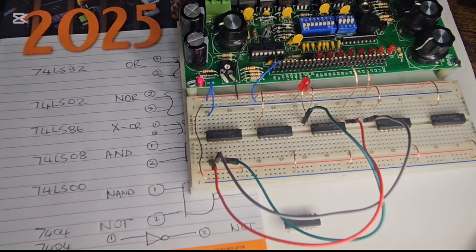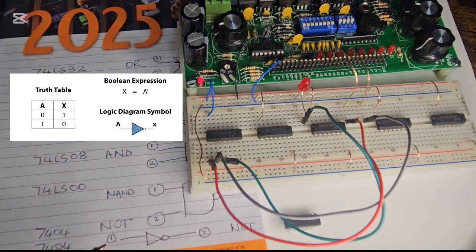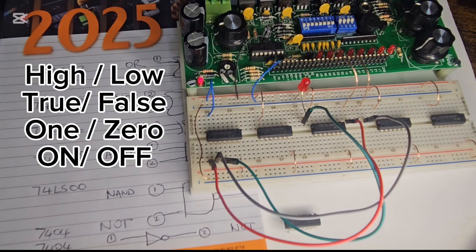So the basic type of logic gate is a NOT gate. Here is the symbol of the NOT gate. This one. A NOT gate is a type of gate that will give you a high output when its input is low. So we're going to be using three sets of words here. We're going to be using high and low. We're going to be using true and false. And we're also going to be using a 0 and a 1.